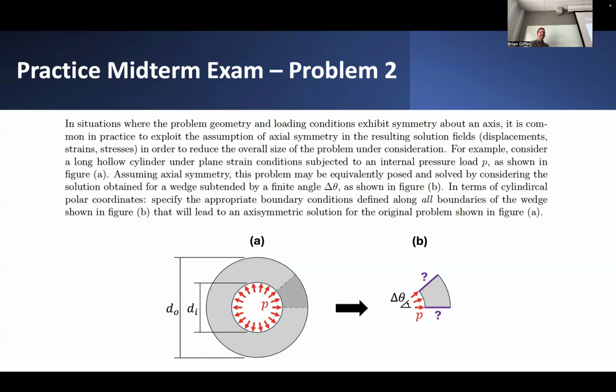Yeah, it's a force per unit area, and it's related to particular components of the stress tensor, depending on the normal direction relative to a given surface of interest. So if I'm looking at some kind of circular arc on the surface, maybe it has a normal direction that looks like this. And if I wanted to define the traction vector on this surface, how is it related to the stress components acting on this block of material?